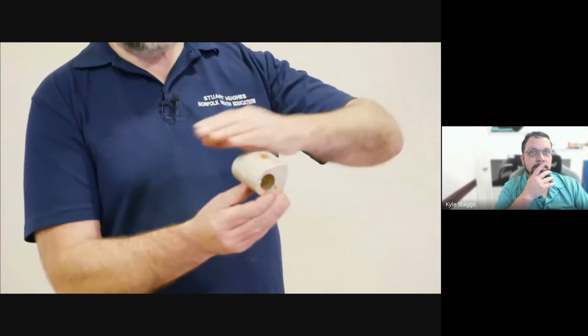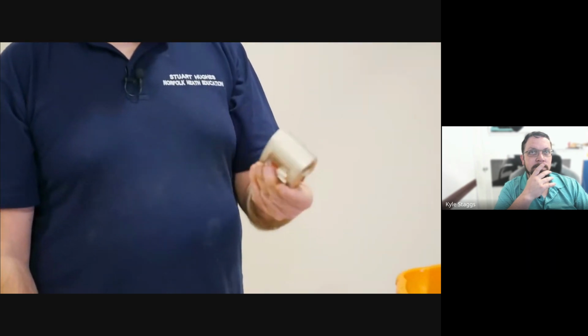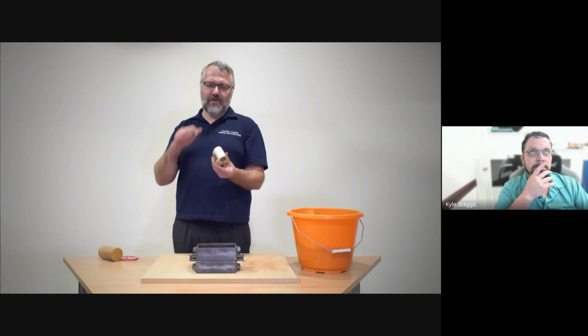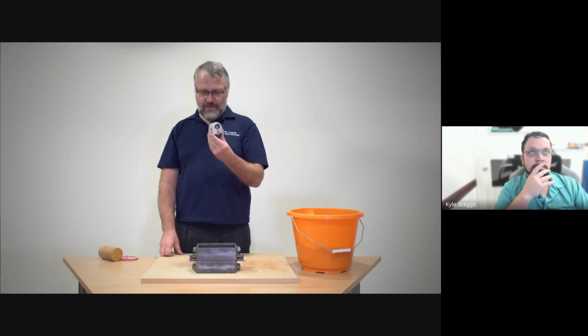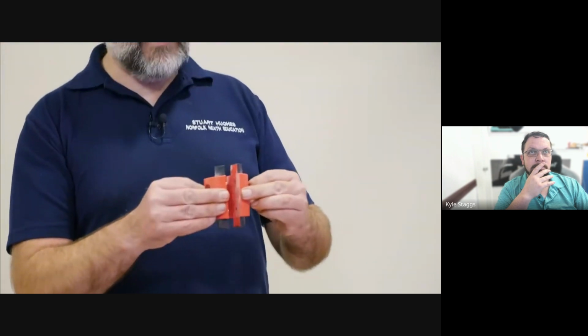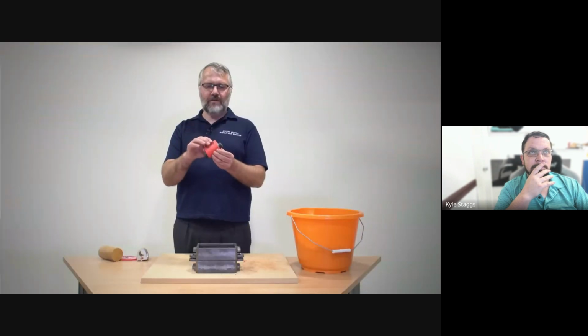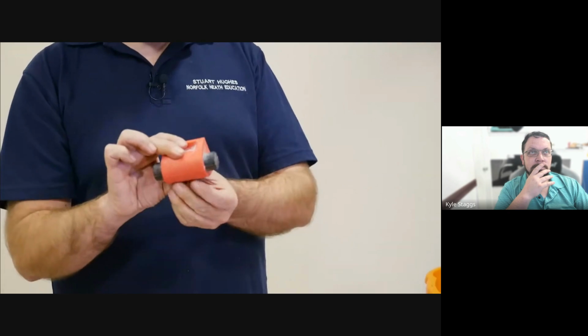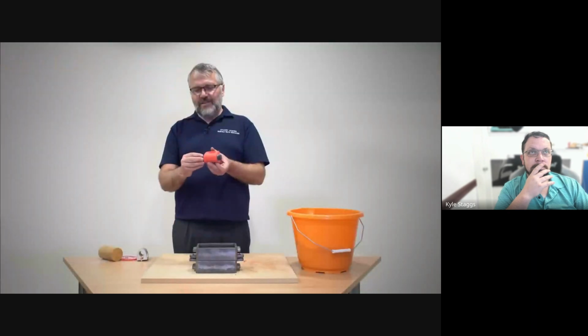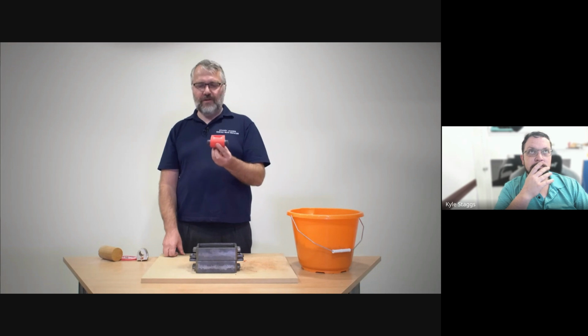We've already thought about using a split pattern so that you can take the two halves separately. But how can we produce the hole through the middle without having to drill it out? In industry, obviously producing something and having to machine a lot of the metal away is time consuming and cost consuming. So producing it with the hole already in place is an advantage. So we're going to use a pattern. Again, it's a split pattern, but it forms together to produce the outside shape. But it has these locating bosses on the ends, which are known as core prints. They're painted black because that's a visual clue to the people in the foundry that they've got to add a core to the mould.